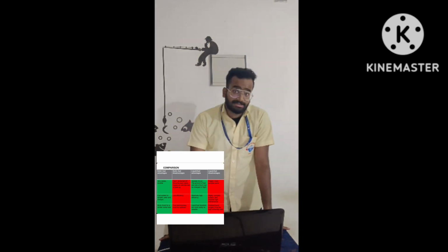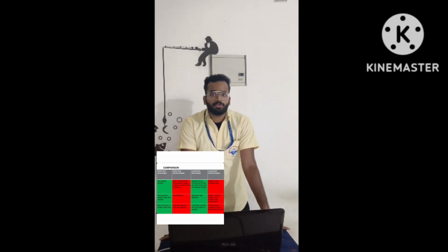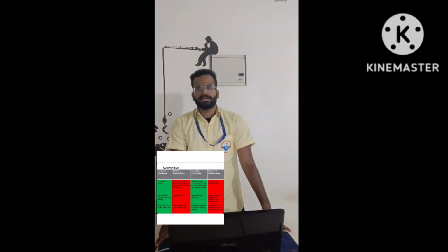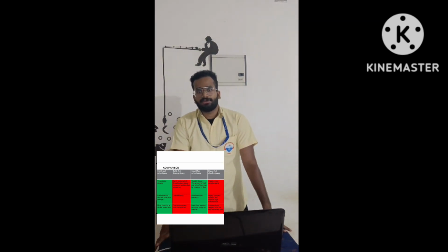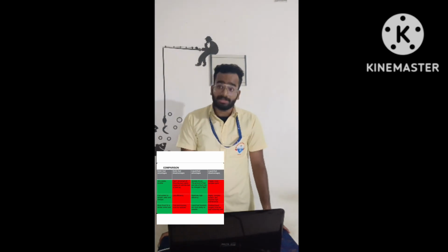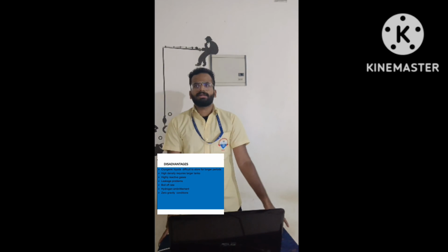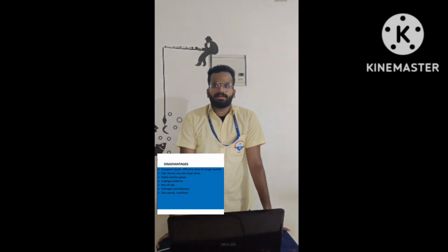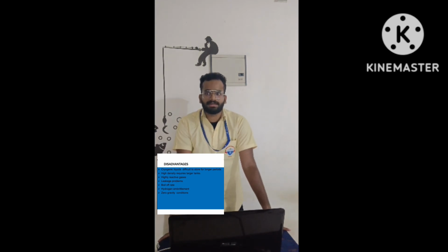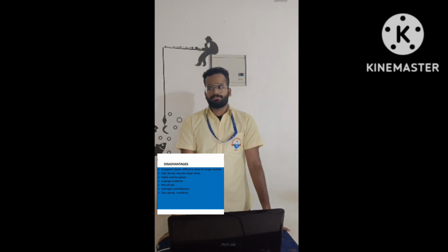Liquid fuel advantages. Variable thrust: the amount of fuel and rate of burn can be changed in flight. Relatively high efficiency. Liquid fuel boosters are more easily reusable. Disadvantages of liquid fuel: fragile, more complex parts, highly complex system, and requires high maintenance. Oxidizer must be kept extremely cold.